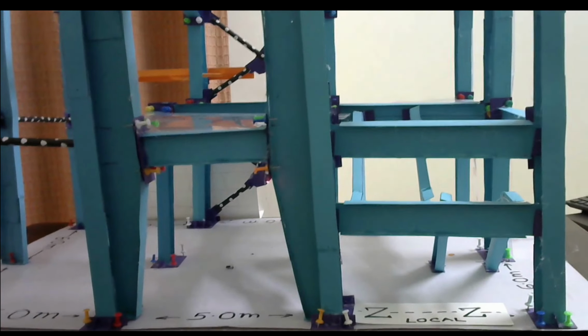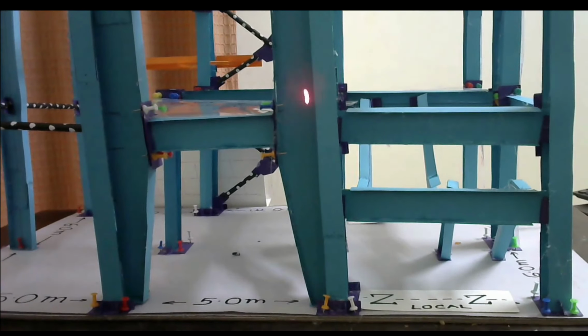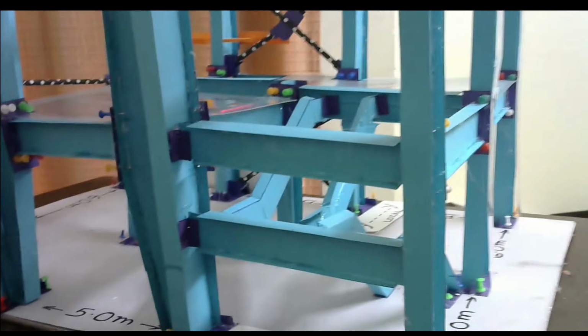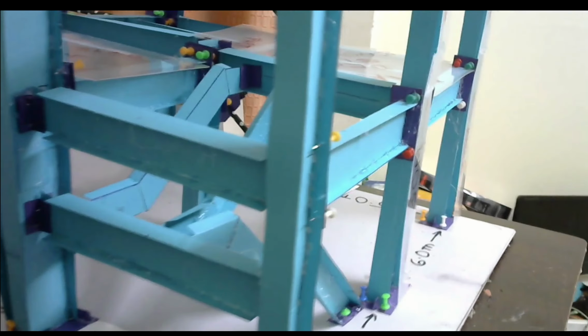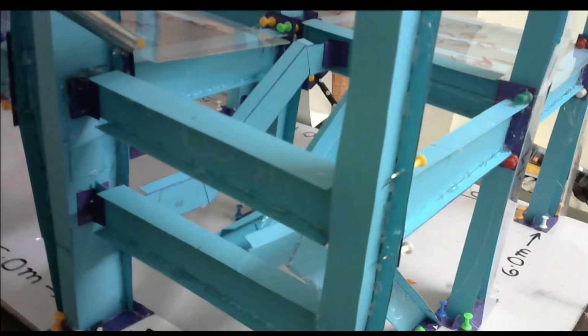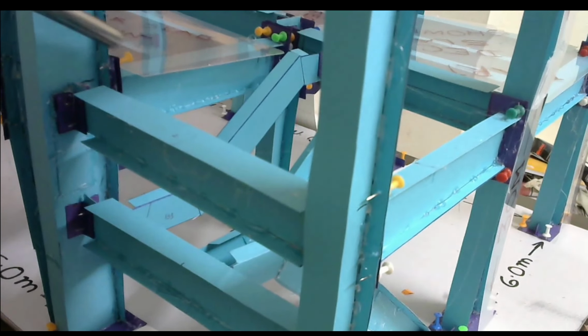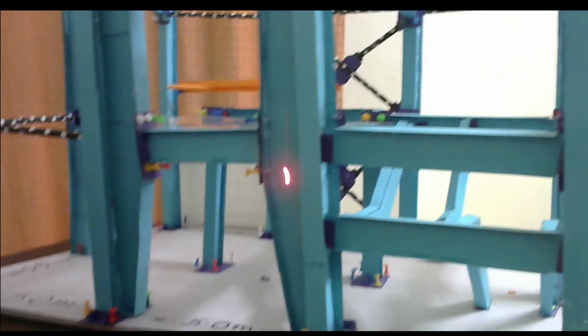Then if we consider LI, we can define it as 3 meter for this portal frame, because there is a moment connection here, but this is connected to the main frame, so we should not consider it. If you see, there is a moment connection here for this main frame attached to this portal frame, but we cannot consider this moment connection as providing fixity about the YY direction of this portal frame because it is not connected to the flange of this portal frame. So we can consider this as providing a simple resistance. So LI will be 3 meter.